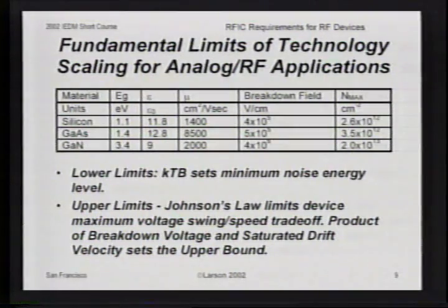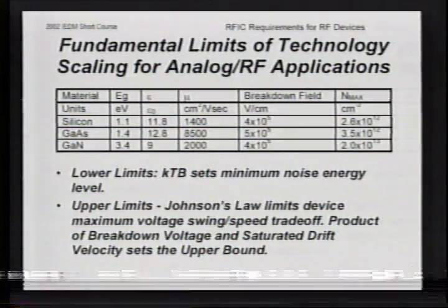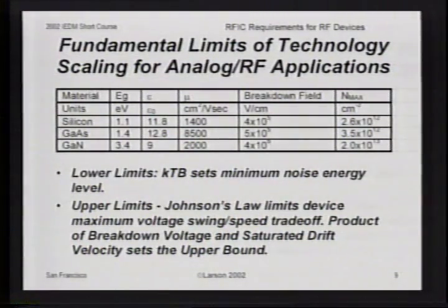Gallium nitride is a device technology that I won't spend much time on today, but it has some real potential advantages for base station power amplifiers in the coming years, and it's a very active area of research within the device research community. The fundamental advantage with gallium nitride is not so much the mobility, which is rather modest, but the breakdown field, which is about an order of magnitude better than even gallium arsenide. So if they can make this technology work quite well, very high power linear amplifiers are a distinct possibility.